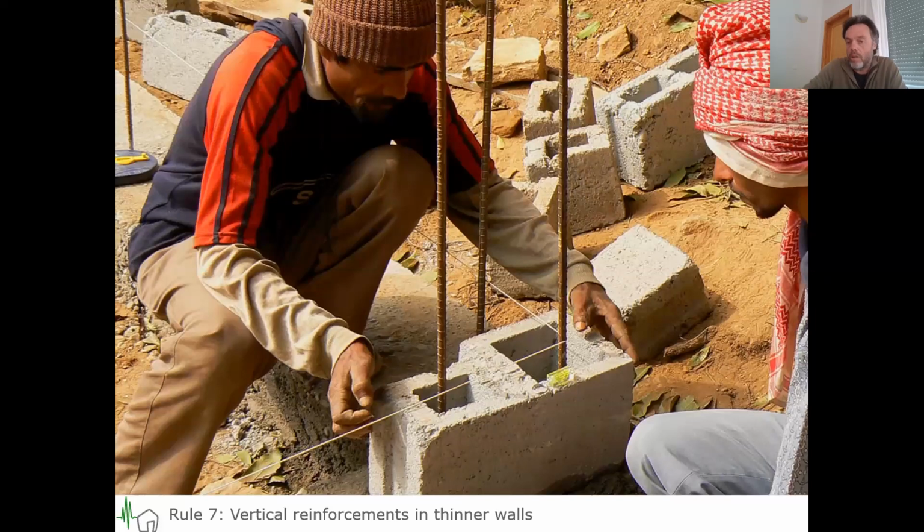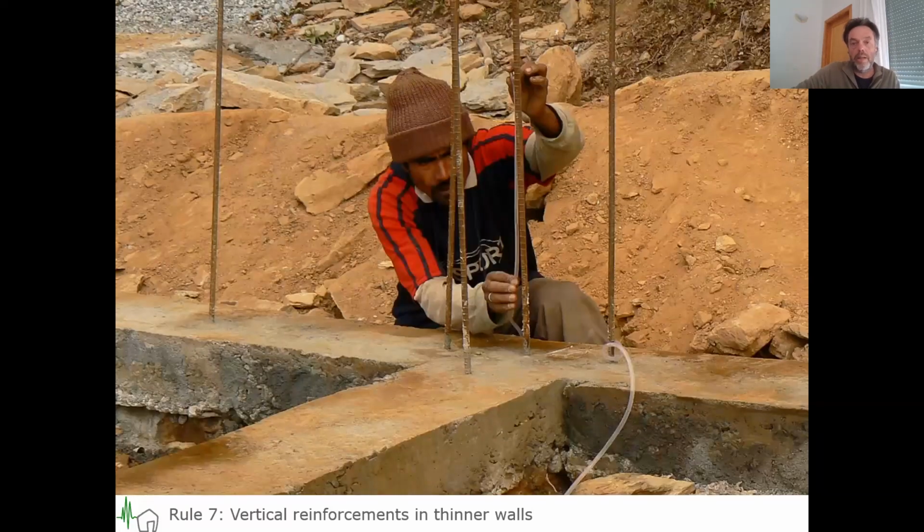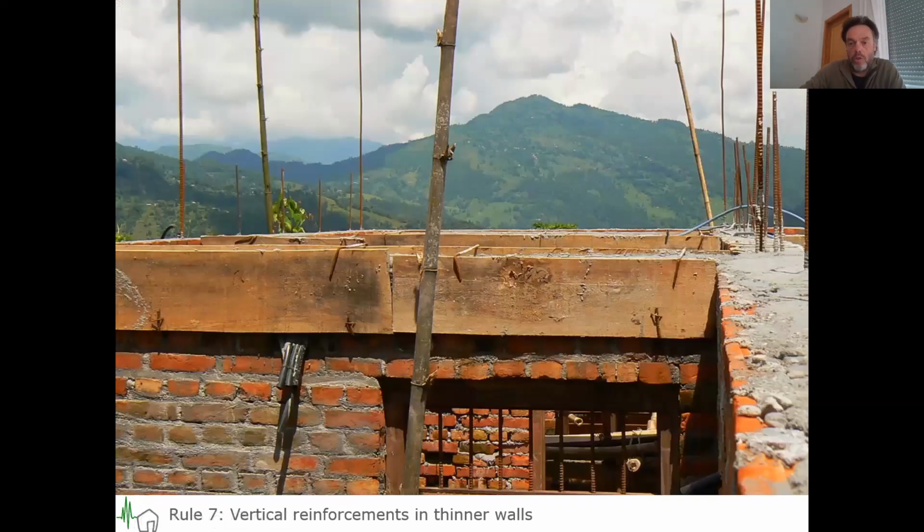I mean, the holes are basically already there. So you start building your wall. You slide the blocks over the steel bars, and then you fill that up with a lean concrete. Here you see it in the T section. There's 4 bars, and the bar that you see here is the one that will come next to an opening. So at the top of the wall, you will see those bars sticking out. That means that this is a thinner wall, which is also reinforced with vertical steel bars.